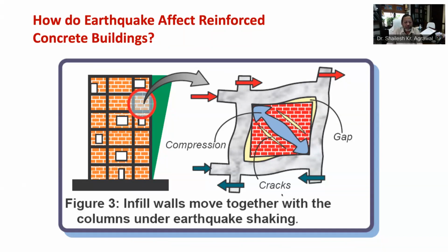As we already know, masonry is a brittle material, and therefore these walls develop cracks once their ability to carry horizontal load is exceeded. Let's consider these infill walls as sacrificial fuses in buildings. This means they develop cracks under severe ground shaking but help share the load of beams and columns until cracking.